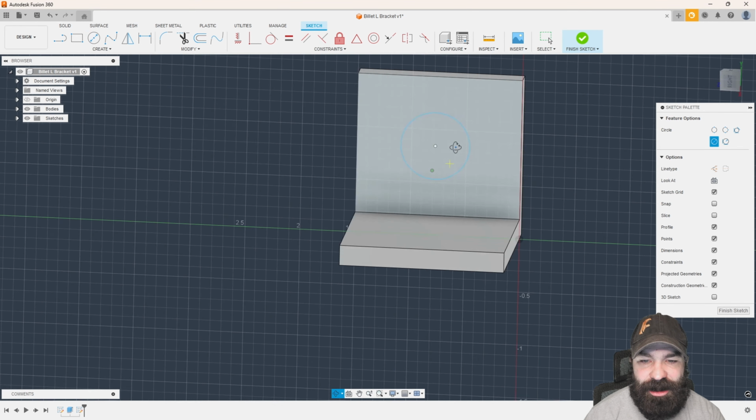I have to be a little careful of where that snaps to, because as you're seeing here, we are referencing that to the midpoint. So if I release too soon, it's going to lock it down to that. And it will make this next step a problem, in the event that I want to dimension this from a certain edge. So I'm going to go off the top edge and I would like that to be 0.625 from the top. I wouldn't be able to do that because that midpoint constraint would be getting in the way. So if you guys have that issue where you can't dimension that, it's all traced back to that midpoint constraint probably being in your way, and you'll see a little triangle right here if you put your mouse on that center point. It looks very similar to this triangle up here.